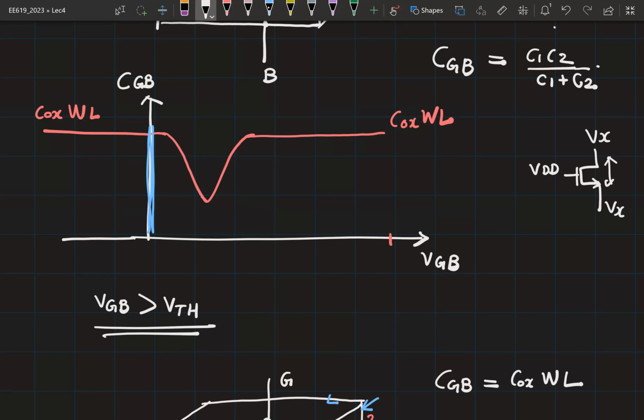So it will be either in linear region or you will simply turn off the switch and make sure that the input voltage is much smaller than VTH. So you're going to work between cutoff and linear region under steady state conditions. Okay. So given that it is operating in linear region, what comments can you make about the inversion layer charge? Is it completely established or is the depletion width still increasing?